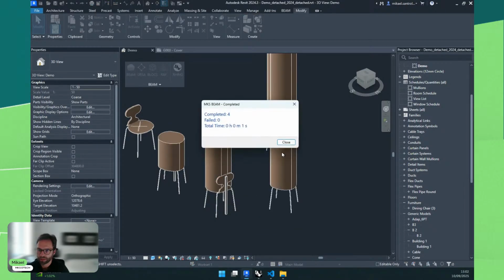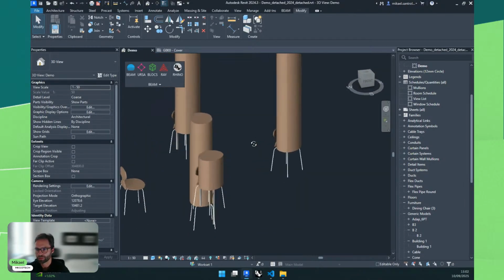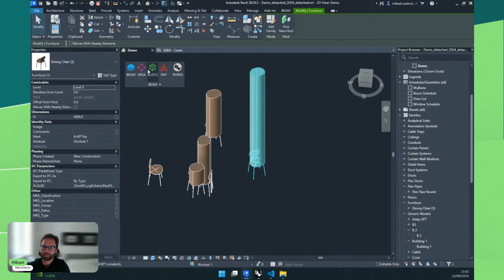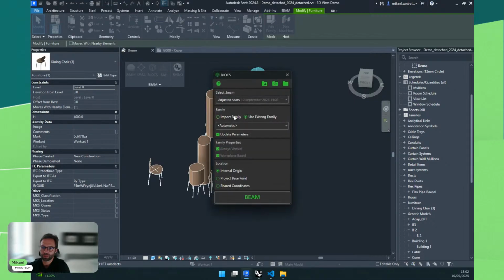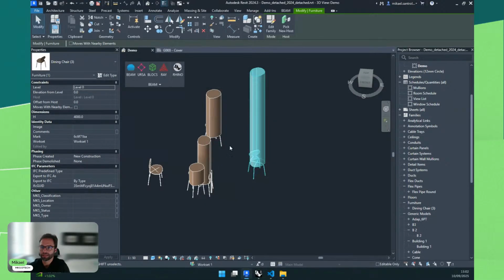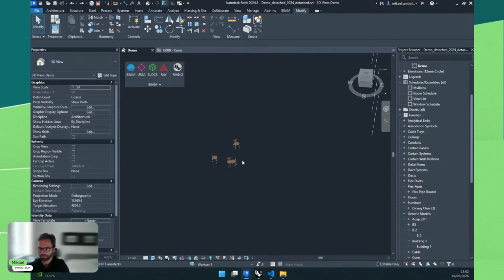As I press OK, you will move them to the location if they were moved, but also assign the instance parameter that I have set. So you can assign material, text, numerical values, whatever you want. So to drive properties of these native families directly from Rhino very easily. And that's with blocks. So many options here that you can use to use blocks, either importing geometry or just driving actually families. Okay. Hopefully everything is clear so far.